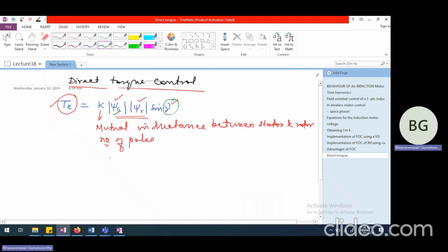As you know, we can say d psi by dt is generally the voltage, the induced EMF, with a negative sign, just to indicate that if the flux is increasing, the tendency of Lenz's law essentially is to nullify the change that is happening in the flux linkage. That's why we put a negative sign. So the induced EMF will work towards reducing its own root cause, which is delta psi itself, the variation in flux linkage itself.